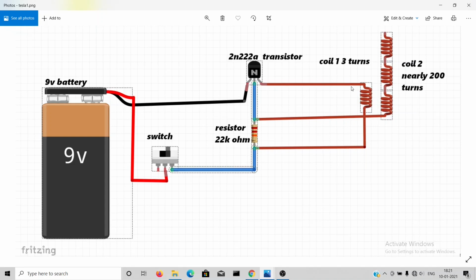By electromagnetism, a current carrying conductor produces a magnetic field around it. The magnetic field produced around the primary coil gets linked with the secondary coil due to mutual induction, which in turn induces an EMF in the secondary coil. By Lenz's law, the induced EMF opposes the change or cause that produces it. Here the cause that produces the EMF in the secondary coil is the current through the primary coil. Hence the EMF in the secondary coil opposes the current in the primary coil. Hence the lower end of the secondary coil becomes negative and the upper end of the secondary coil becomes positive.